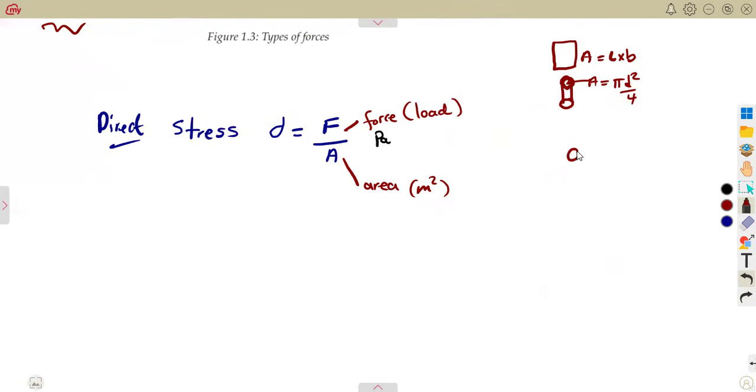Is it a condition where you have something of an annulus, where there's a smaller diameter inside and a bigger diameter of the outer circle? The area is going to be pi over 4 times D squared minus d squared. Depending on what you're given, the shape will affect your area in square meters, and also those conversions, as you heard from your engineering science, they do not change.